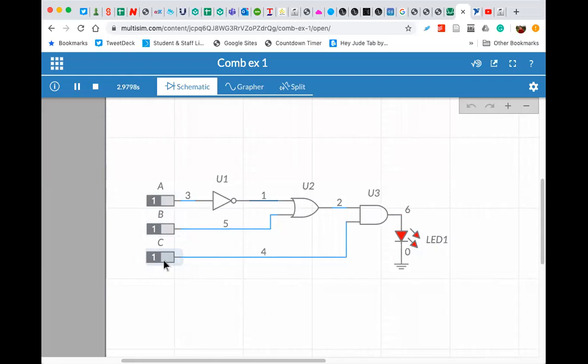So that's how you exhaustively check the digital circuit. You must check not only that it turns on when you want it to turn on, but it doesn't turn on when you don't want it to turn on. So you're checking not just what you want it to do, but you're making sure that it doesn't do what you don't want it to do. Everybody get that?